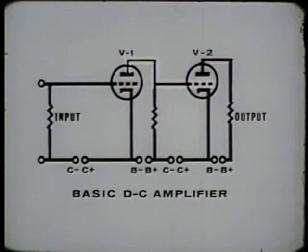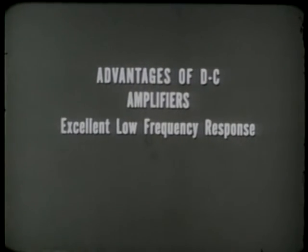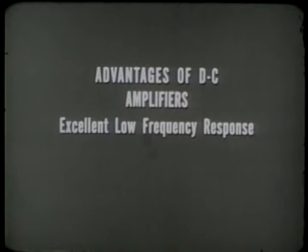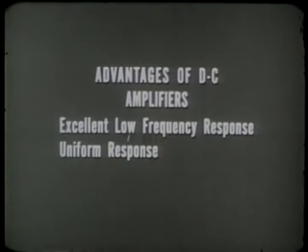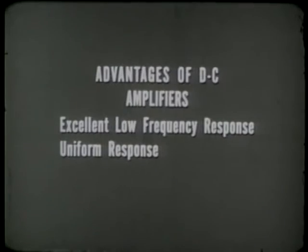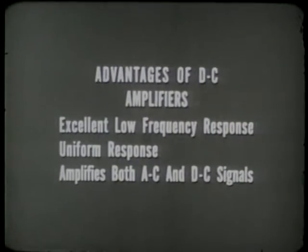Direct coupled amplifiers have several advantages. One, it has excellent low-frequency response. Another advantage is that the response of DC amplifiers is the same for slow variations as it is for non-varying signals. And a direct coupled amplifier is suitable for amplifying both alternating and direct current signals.